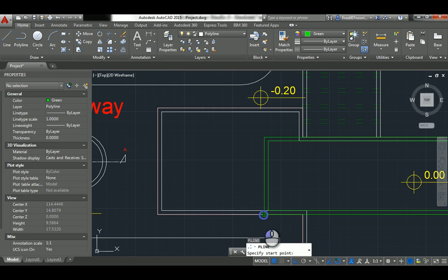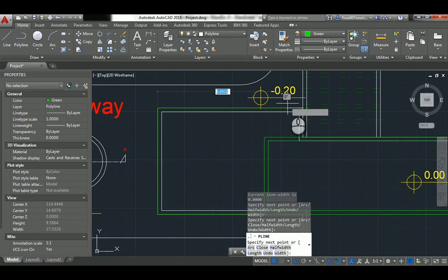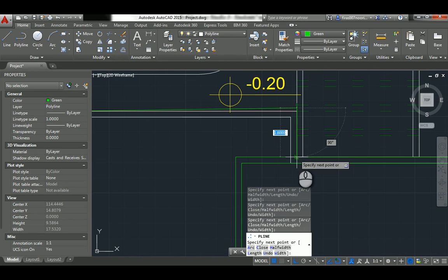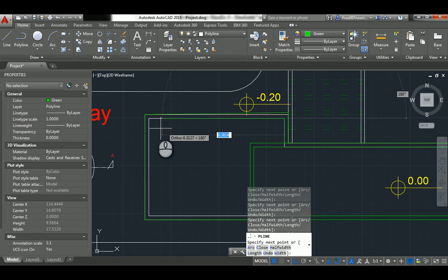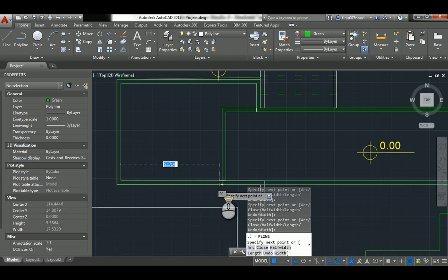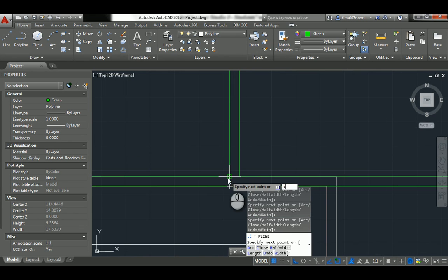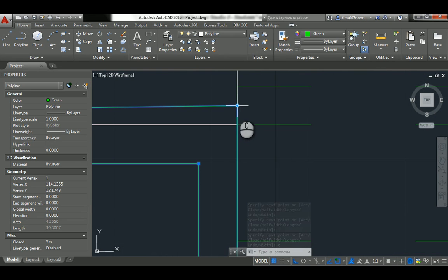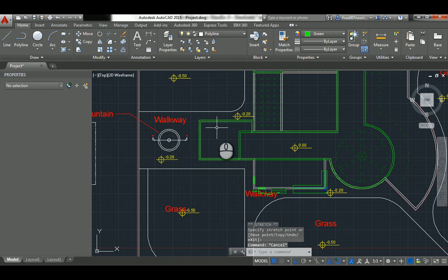starting from here, it's good to have the first floor here, which is the greenish one, or the green shape you see here, and here, and so on. I made a mistake, if you noticed, in clicking in the wrong place, but it's okay, we can fix that easily. And here you must hit C space to close the profile, the full line. And here you notice that I made a mistake. It's okay, just drag that to the correct location, and then use the write block command to export that